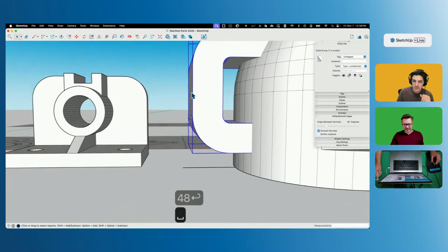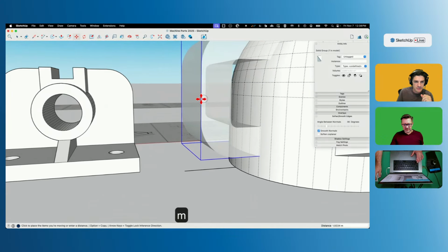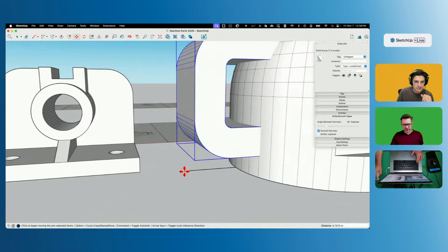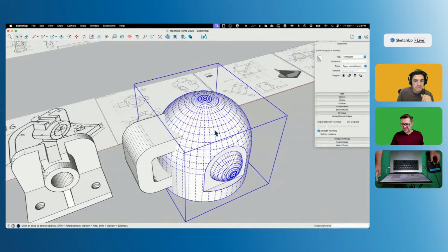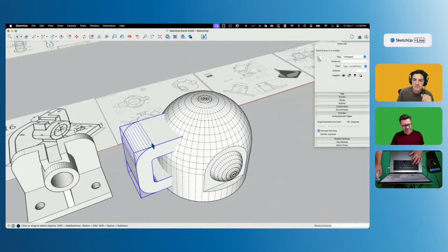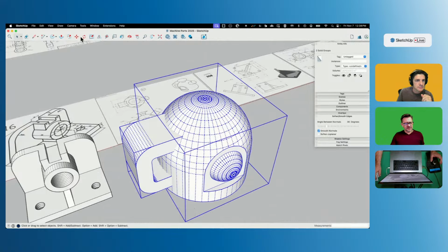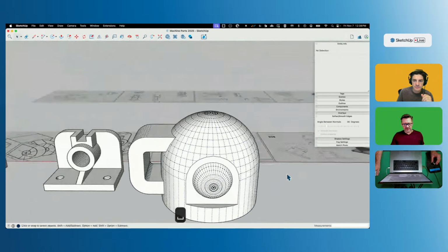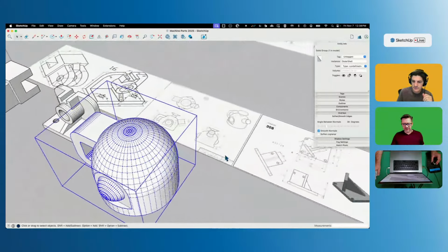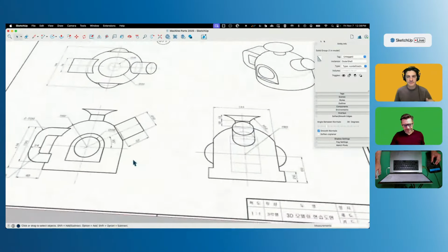And I know now if I move this piece horizontally so it hits that point, now it's in the exact right spot. And again, let's see, solid group, love it. We'll grab both of these, go to tools, outer shell, boom. There we go. We got one big solid group. Last two things on here.